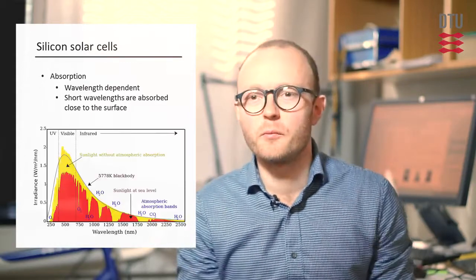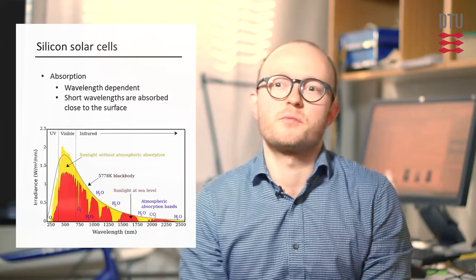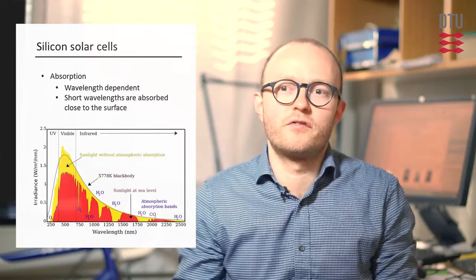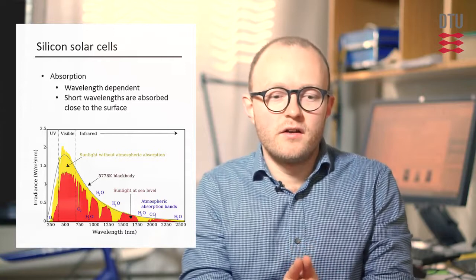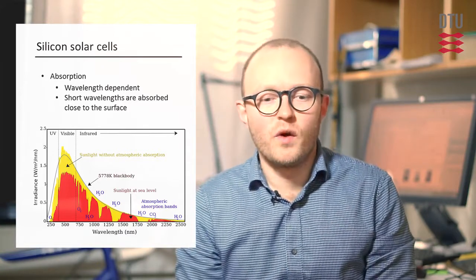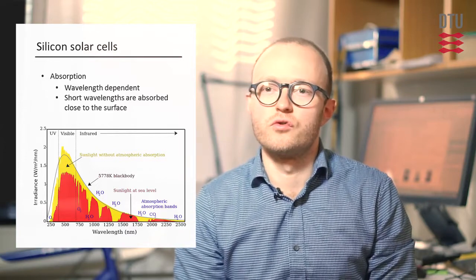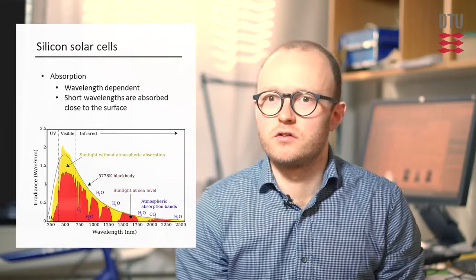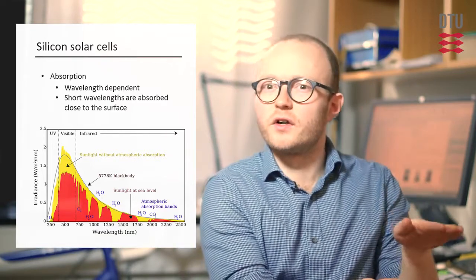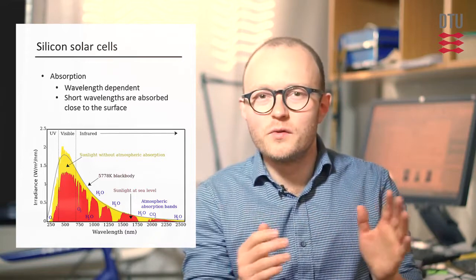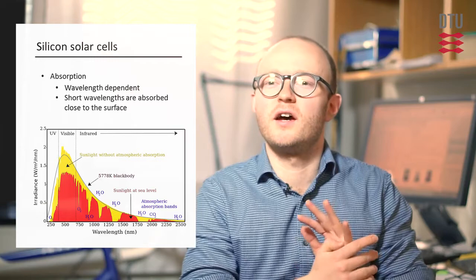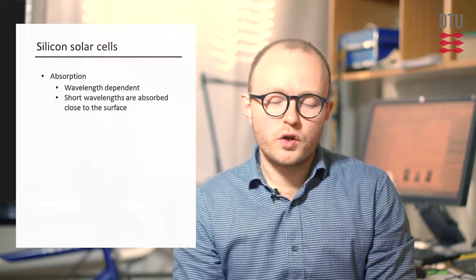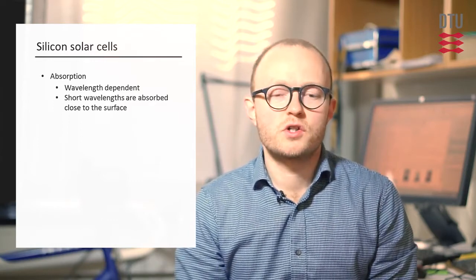So if we look at the solar spectrum, the infrared and the near infrared part of the spectrum is actually very important to optimize the output of solar cells, and therefore the red and infrared wavelengths are difficult for silicon solar cells to absorb and to get the full potential out of. In order to solve this, a lot is being done in silicon solar cells, besides having a sufficiently thick wafer, which doesn't solve everything, because we can't pay an infinite price of just going to thicker wafers. What is being done instead is to try to achieve what's called light trapping.